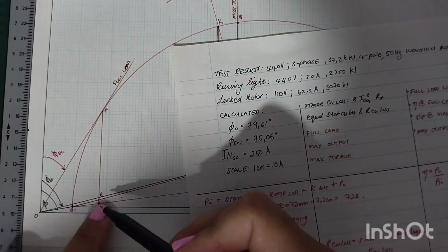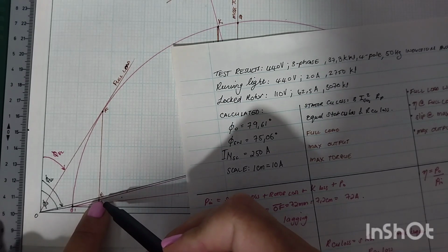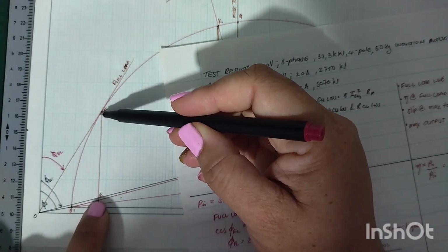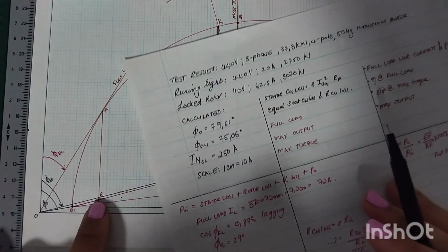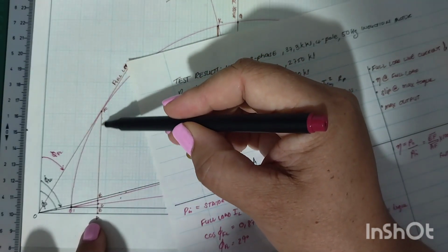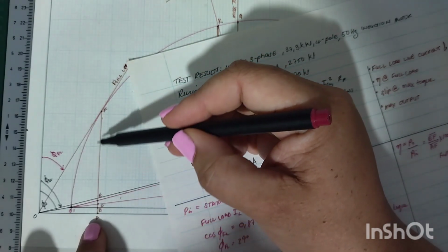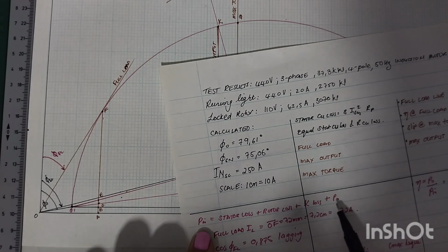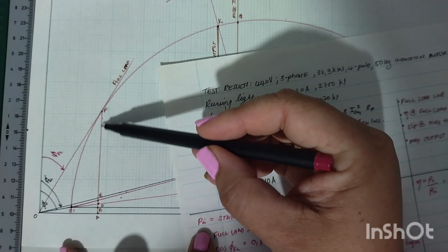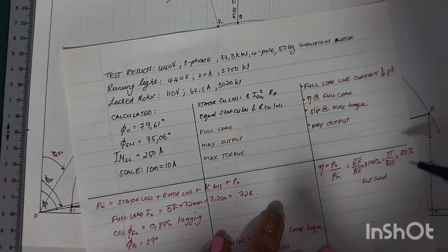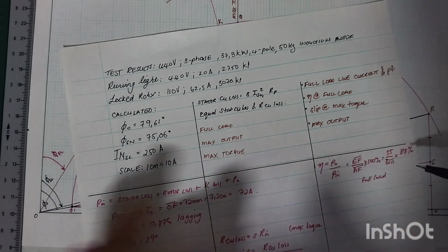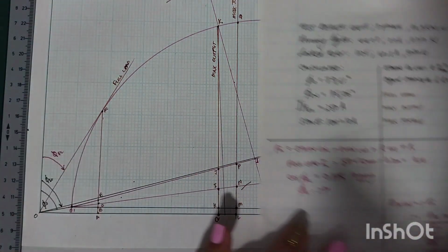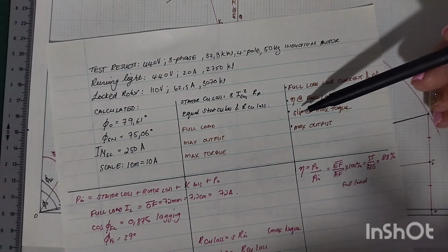So again, your power out is from your output line to the perimeter of your circle, always for any condition, for any load. And your input power would be the entire length of that line which you draw perpendicular to your horizontal axis. Should make sense to you that your input power is bigger than your output. So it's the whole length from what I marked out to be A to F. So power out over power in, that gave me efficiency of about 88% in this case. I did not need to calculate the associated power. So for max output, for max torque, anything, any condition, same thing applies.